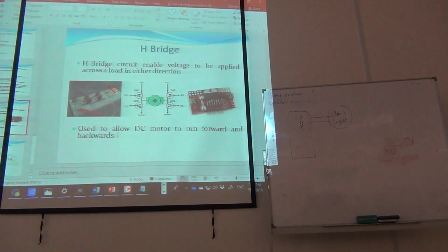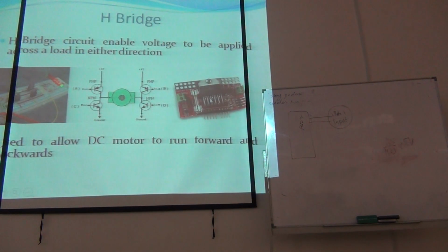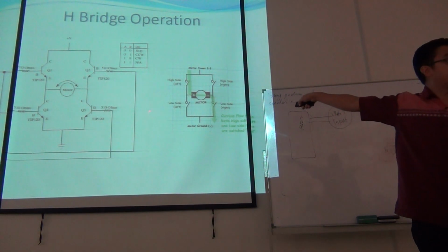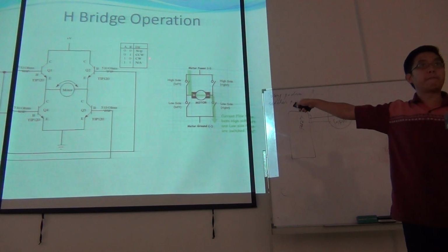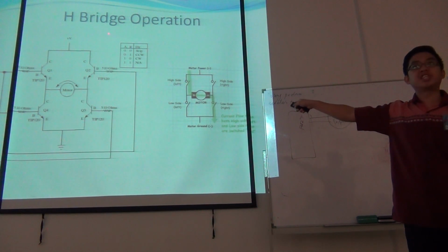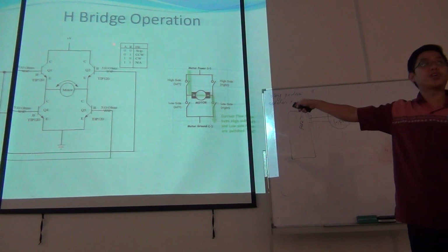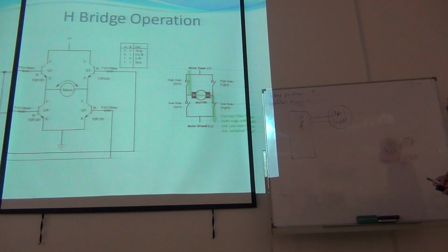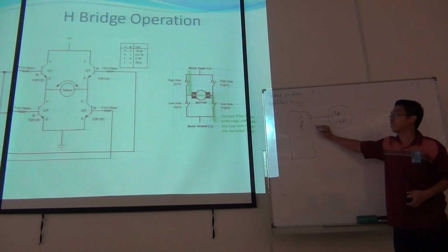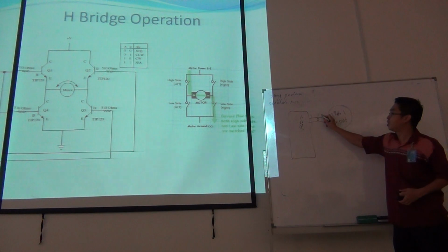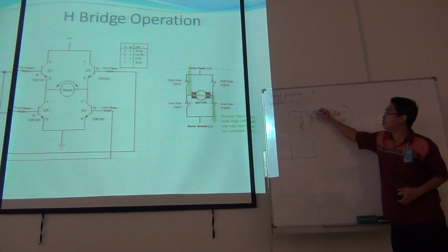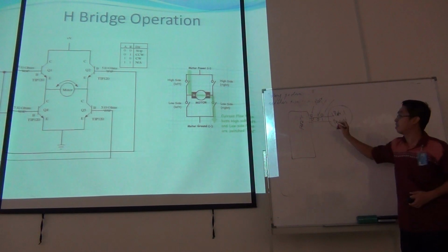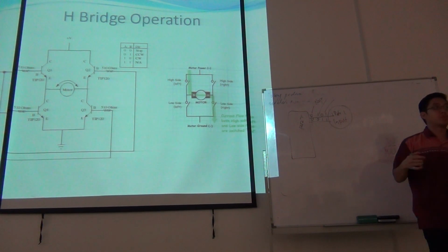What does the H-bridge say? You have to control according to this particular table, either to stop, or to go in one direction, counterclockwise, or you can stall the motor. Stop means jamming it. So here is the one where you need to generate the signal, either 1 or 0, or 0 or 1, or 0, 0 for nothing, no speed. This is one direction and this is another direction. If you put 1, 1, it will jam the motor.